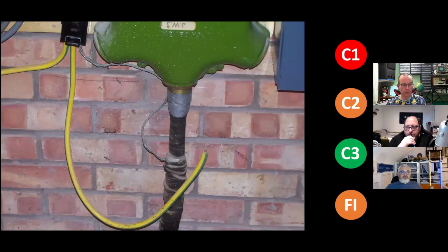Now, interestingly enough, the insulated Henley blocks, they're provided by the DNO and they're deemed DNO equipment under their own standards. So it's another interesting one. So evidently an electrician has gone in there and connected that and then left it for the DNO. That's what it looked like to me. It looked like that earth had been left for the DNO to connect onto.